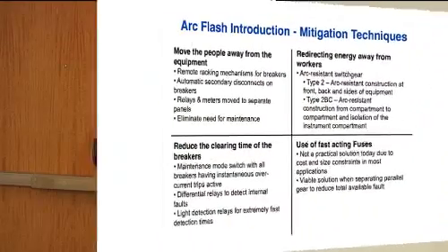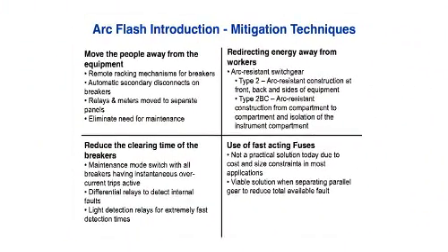The next one here is if you're talking about non-arc-resistant switchgear, what's the best thing you can do is take the relays off of the switchgear and put them on separate racks somewhere away from the switchgear. And what are we trying to do? We're trying to create a larger barrier distance between the product, i.e. something that's going to be worked on. Remember my analogy to 90% of all work being done in the low voltage compartment? Well, that's what this is all about, the relays and the meters. Let's get them out of the switchgear, put them someplace else.